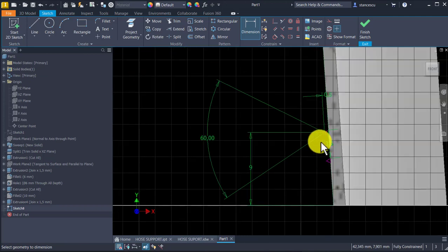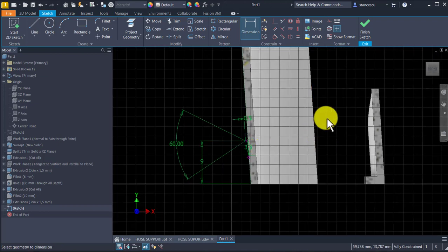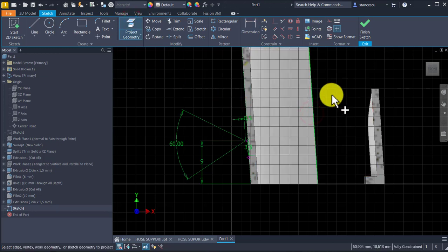And now I create a sketch for axis, this is the axis, so that I must project it. I make it construction. I apply offset of 0.3, as you remember, I hope, 0.3.